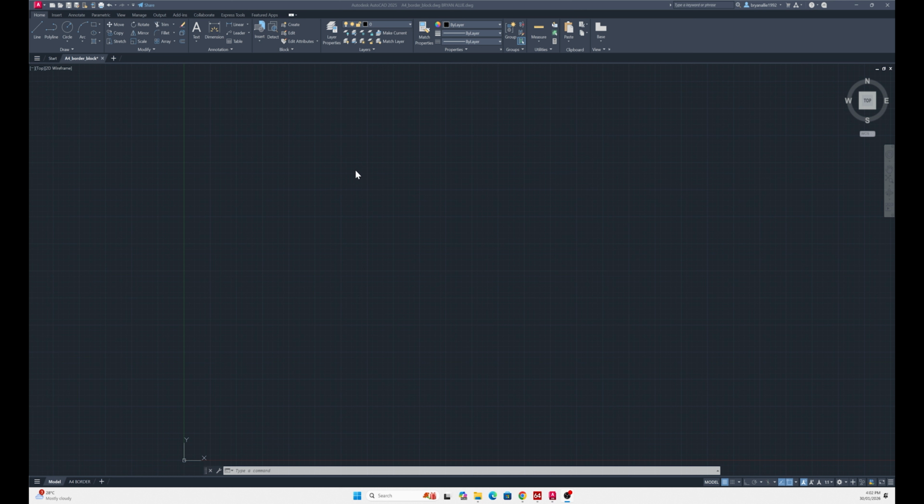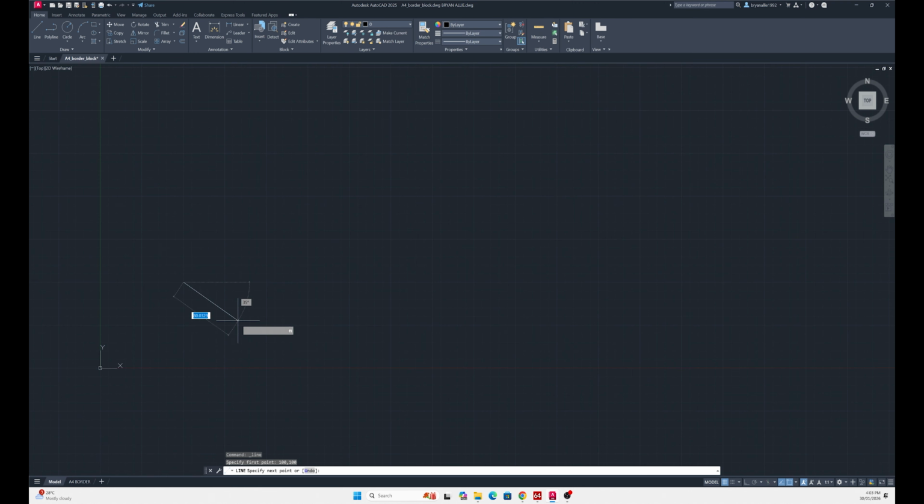So in this particular case, it says point 1 is at 100 by 100, which is our starting point. So if we go up on our little commands here, we'll go line command. I sometimes do polyline, but I'll do line. I'll click again, so you get this dialog here that asks specify first point. So that's what we want. So first point would be the x, so left is obviously x, right is y coordinate. So we go 100 and we go tab, takes you over to the next one. We go 100, enter. Now that's taken us to our 100 by 100.